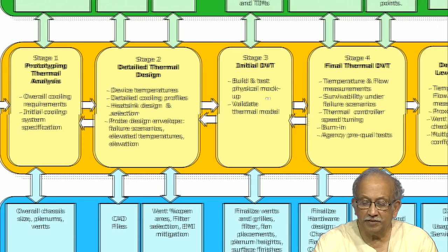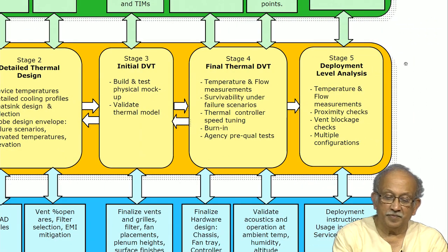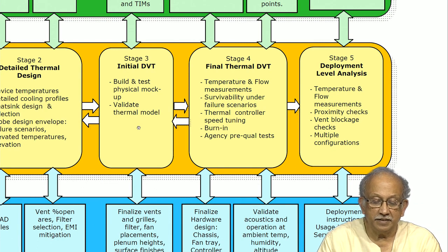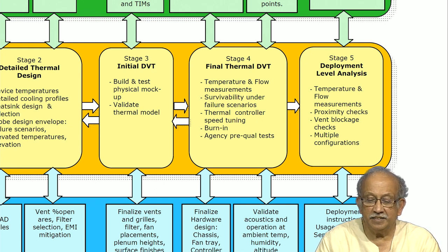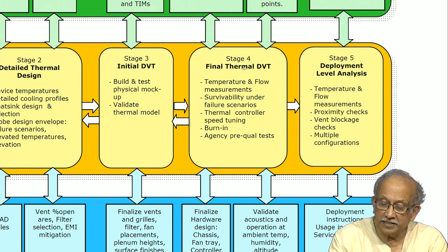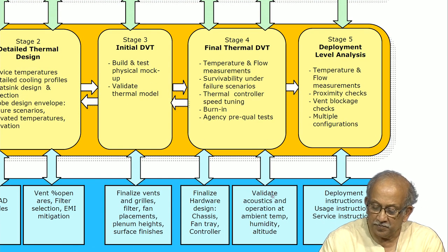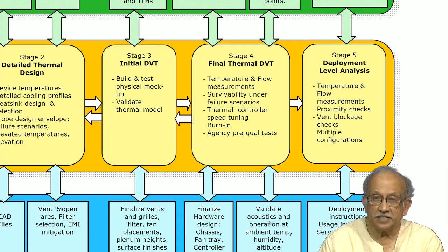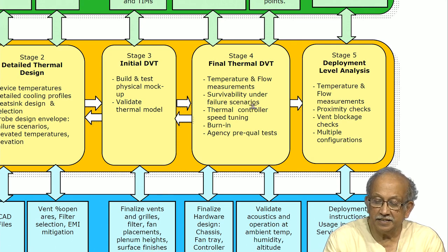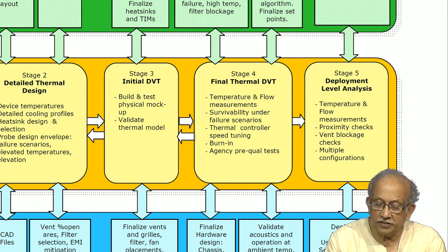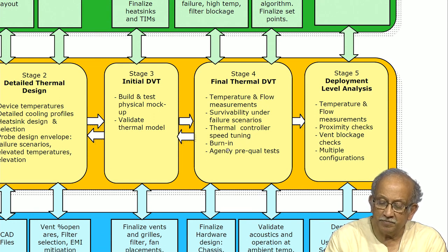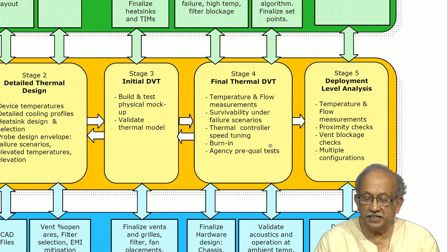So, we build and test the physical mock-up, validate the thermal model. Thermal design validation is very important, and final thermal validation comes to this: validate acoustics, operation at ambient temperature, you have seen this here, and altitude. So, acoustics and operation, thermal temperature and flow, survivability under failure, thermal controller, burn-in, agency pre-qualifying tests, these are not easy.